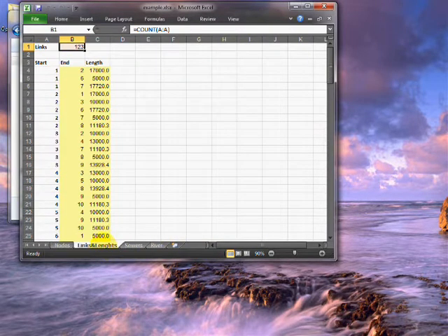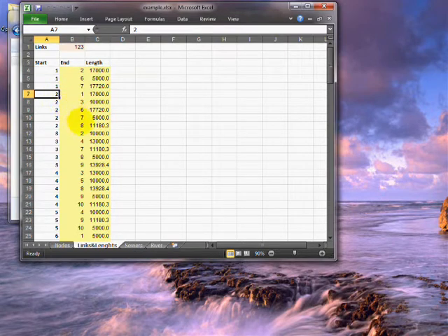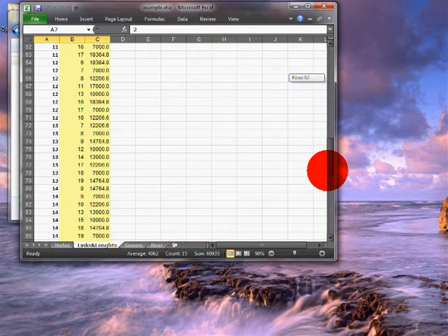The second sheet contains information about all the possible sewers between the nodes. The columns correspond to the starting node, the end node, and the distance between them. For instance, node 1 can be connected to node 2, node 6, and node 7. In this example, there are 123 possible links between nodes where sewers can be installed.